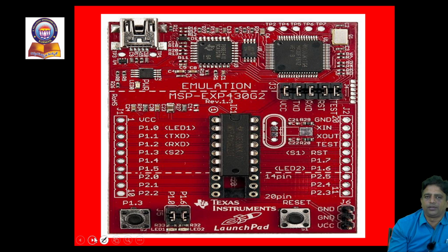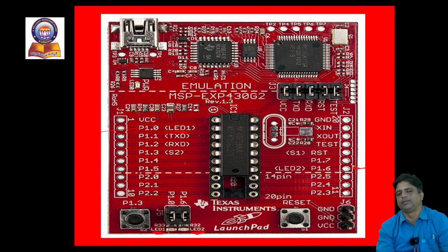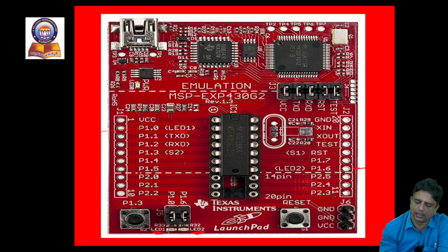Before going for some more practice level, we can look over the practical hardware that we are using. Why we mentioned two names like P1.6 and P1.0 for our operation is, we could look over this. P1.0 has an inbuilt LED arrangement on the launch pad of MSP430. LED 2 of the launch pad is connected to P1.6. It is not a rule that we should use only P1.6 or P1.0. It is only a support, helping for practicing and for learning purposes.